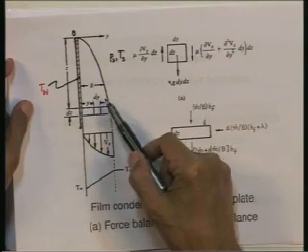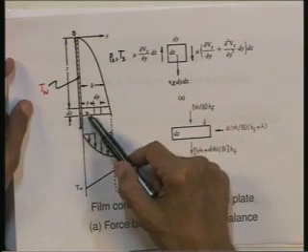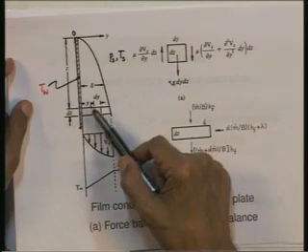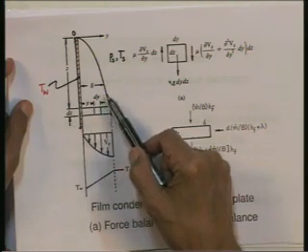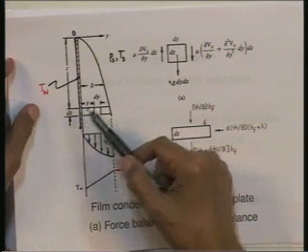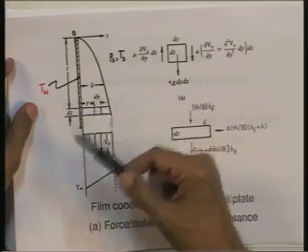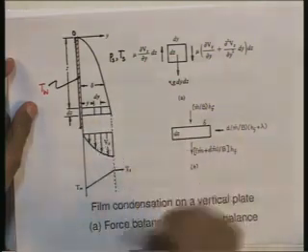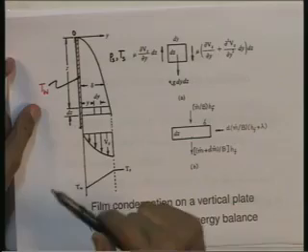So, that is the subcooling that is taking place in the liquid condensate. Nusselt said these enthalpy changes associated with subcooling from T s to T w are negligible compared to the latent heat lambda that we will have to take account of during the change of phase, and that probably is also an exceedingly good assumption to make.